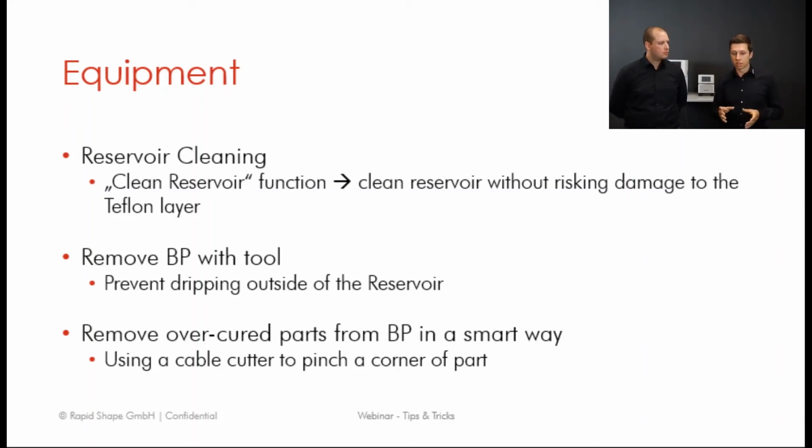Now, of course, if you're for example adjusting the platform a lot, you can see, maybe I can show it to you, there's now a gap in between. This gap can differ by a few millimeters already. And of course, we set the Z-axis limit switches pretty close to be printed with everything. But if, for example, the platform is adjusted in a different way than it was in the original state, it might be possible that this is touching the bottom limit switch.